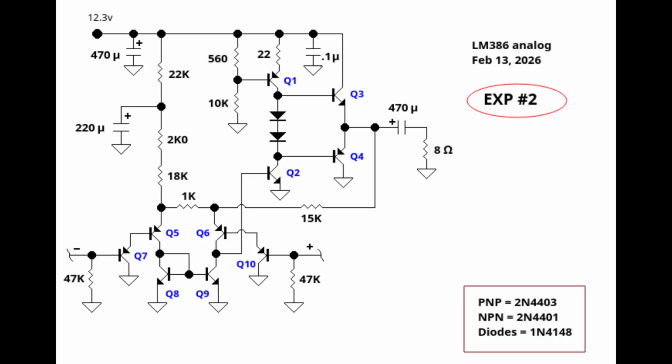In the classic pair of emitter followers, the collector to emitter saturation voltage plus VBE keep you from getting close to the rails. So in most audio amp ICs, you'll see the finals configured other than as a complementary pair of emitter followers. I completed experiment 2.